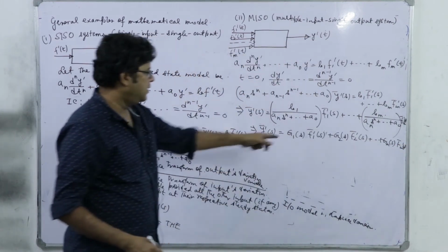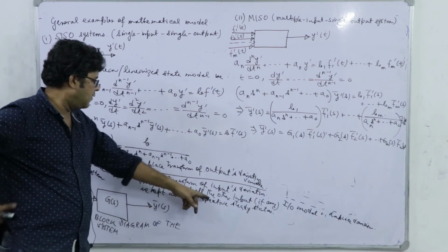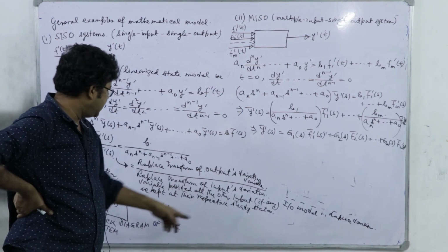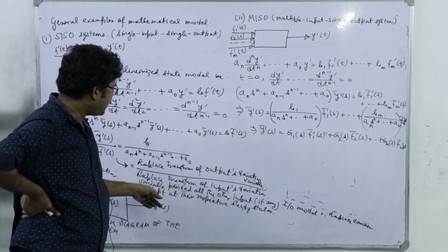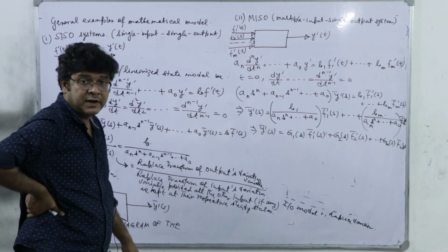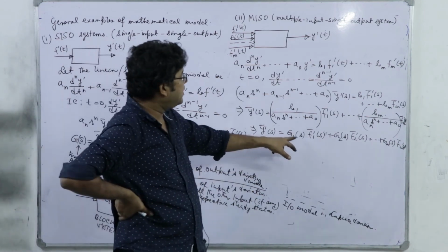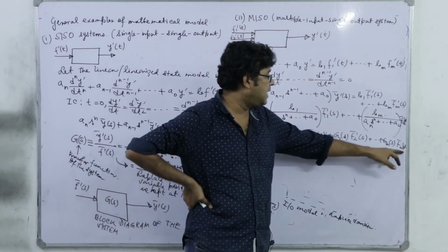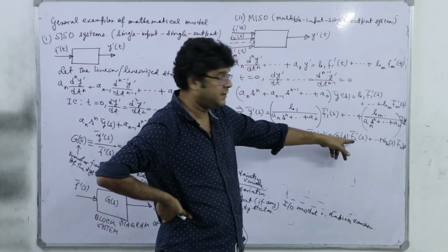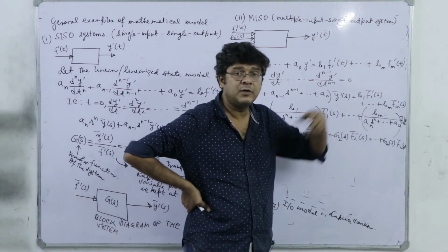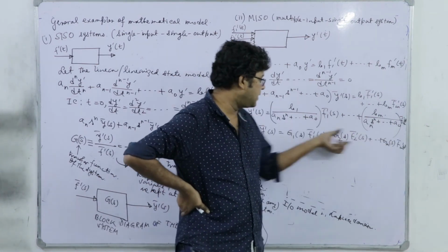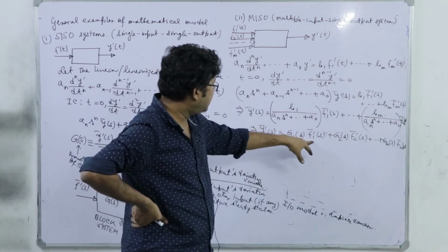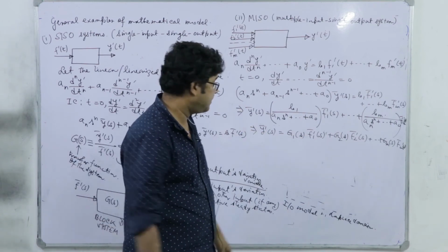So, you see here we can understand the implication of the last part of the statement, that all the other inputs, if any, we are keeping at their respective steady state. If I am thinking of the definition of G1, we are keeping all the other forms of input at their respective steady state. So F2 prime, F3 prime up to Fm prime are all 0. So this part vanishes and we get G1 as a transfer function of F1 connecting Y.